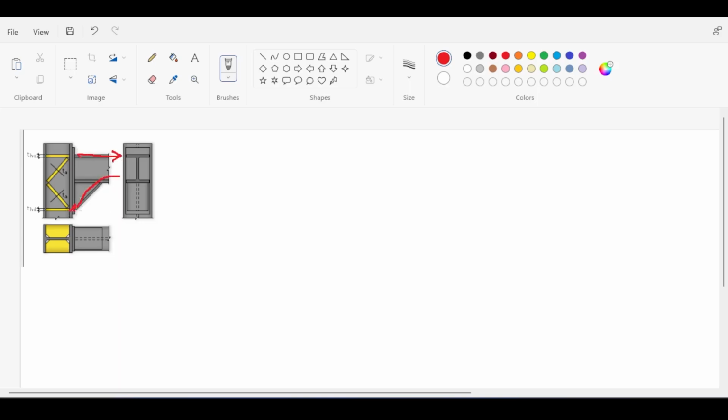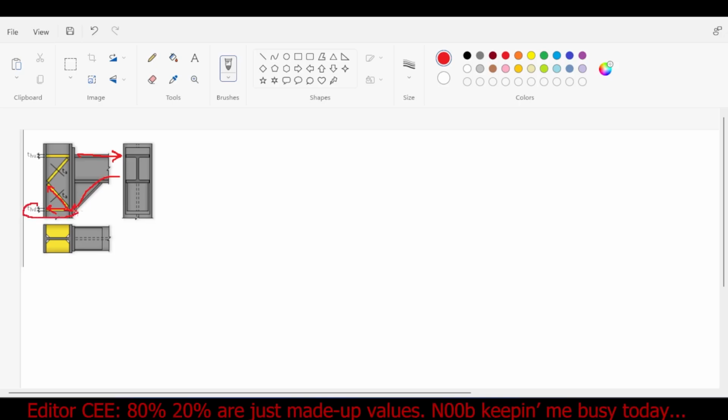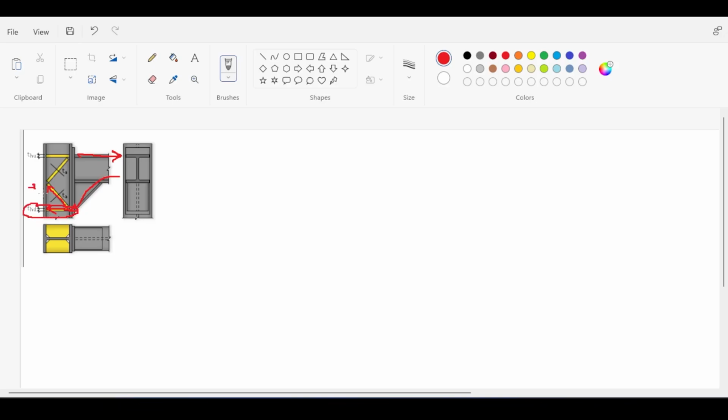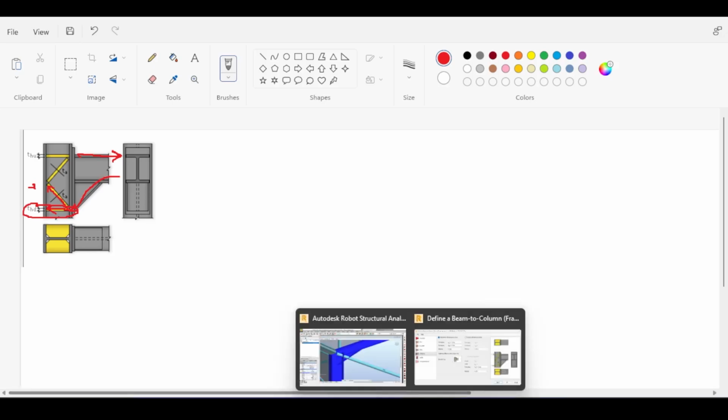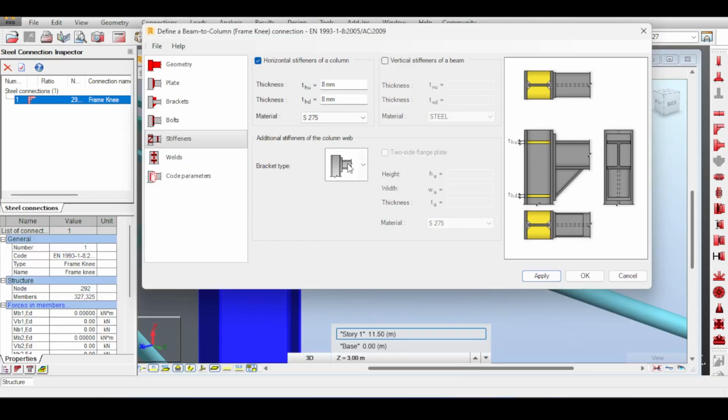this. Okay? And sometimes even the compressive forces might be too powerful for the stiffened flange to carry, so you would take part of the compressive force and distribute it along the length of the flange, which means that like 80% of the compressive force will be resisted by this, and like 20% will be resisted by this. It's kind of like shifting part of the forces to another region to help out in carrying that force. This is something that you do not usually see in ordinary structures, so I leave it.